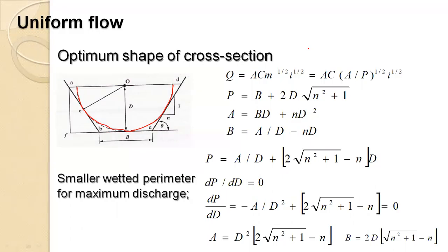But if it is going to be a very wide channel, then the construction is going to be very difficult. Now you're talking about meters, maybe 20-30 meters or even more when it comes to the width of the channel. I wouldn't say you can't, but it is practically difficult to construct circular channels or channels with circular sections. So generally the rectangular sections or trapezoidal sections are preferred.